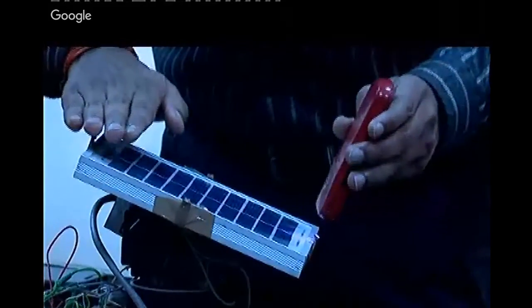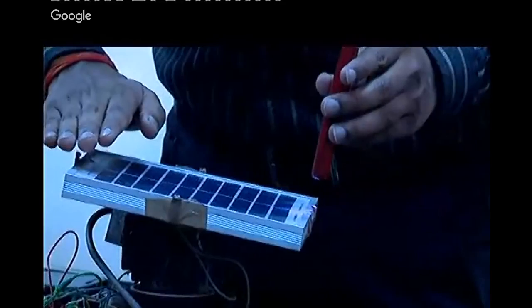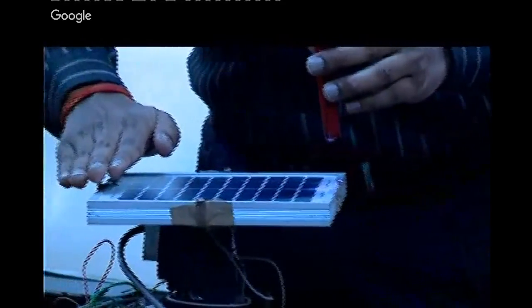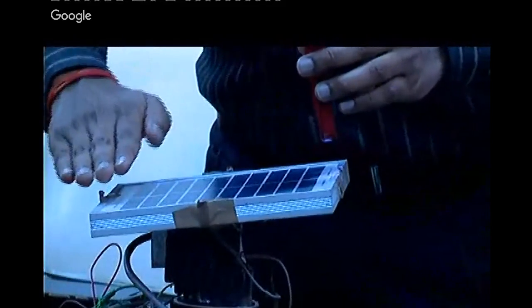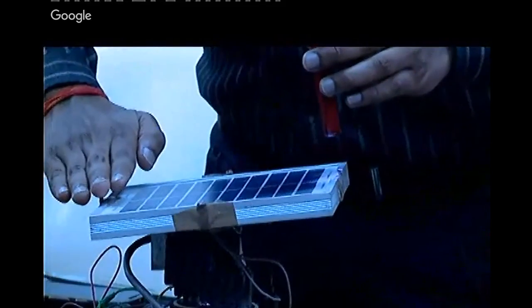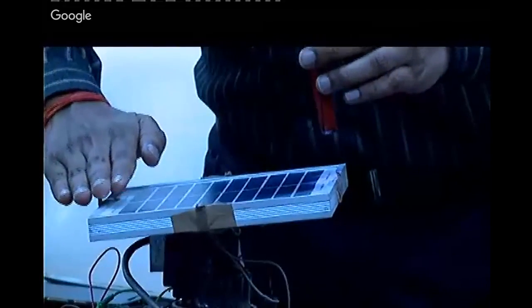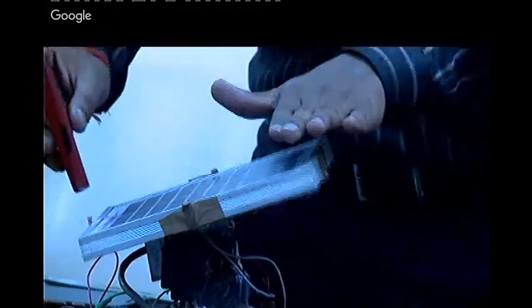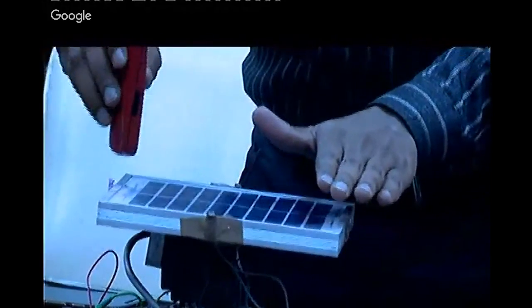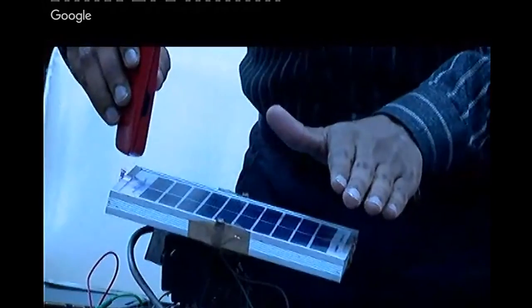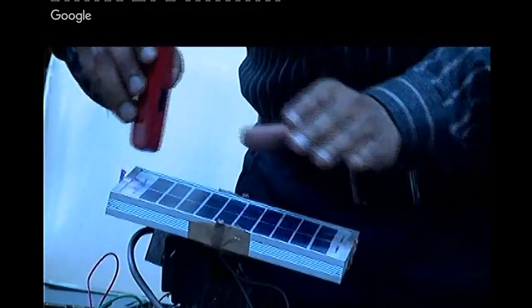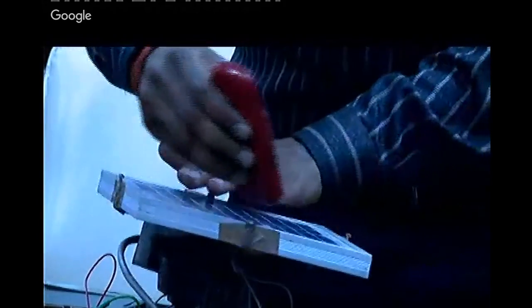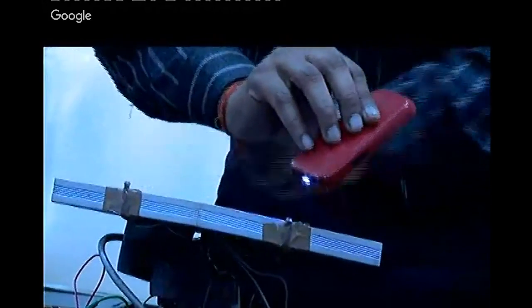If I give the flash so that one side is dark and one side is light, then it is rotating, and this is the movement on the x-axis. You can see I am hiding the light from one LDR and giving the light to another one. It is rotating toward the light. We can vary the speed of the motor by using the PWM pin I have explained earlier, and you can see another movement, this is the movement for the y-axis.